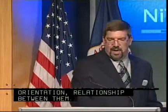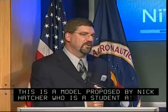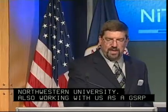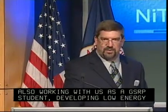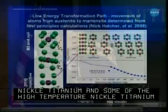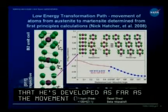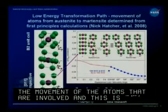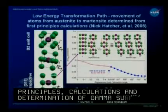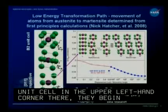This is a model proposed by Nick Hatcher, who's a student at Northwestern University. He's also working with us as a GSRP student, developing low-energy transformation paths in the nickel titanium, as well as some of the high-temperature nickel titanium ternary alloys that we have. And this is one of the models that he's developed as far as the movement of the atoms that are involved. And this was calculated using first principles calculations and determination of gamma surfaces. But if we start again with the original B2 unit cell in the upper left-hand corner there, and we begin to rotate it so that we're looking down only on an 011 perspective of the cell.